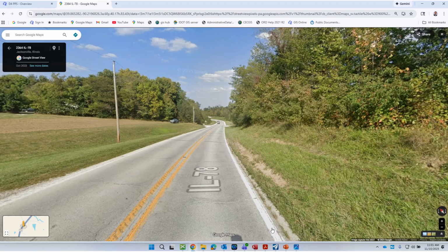We've got that 2-lane pavement, we've got that existing gutter, not just one gutter, it's actually like a double gutter. They used the initial gutter that was on the 18-foot pavement really as like a base course almost. They just resurfaced over that, and then they piggybacked on an additional gutter. So yeah, we're just proposing to remove all of that gutter.